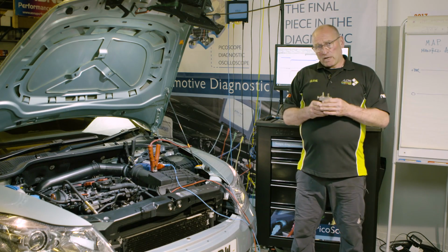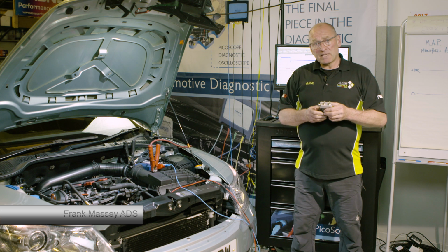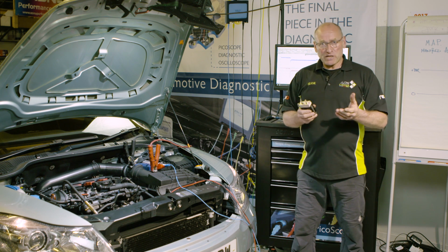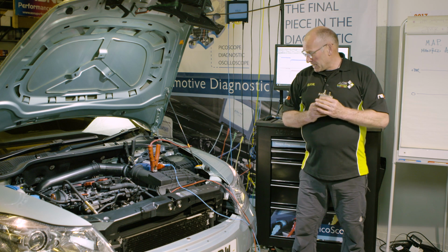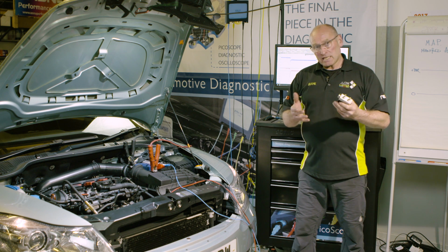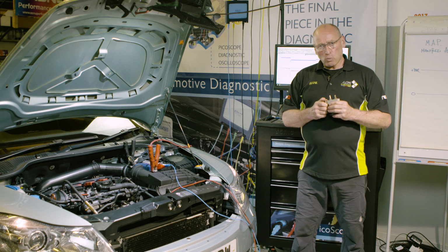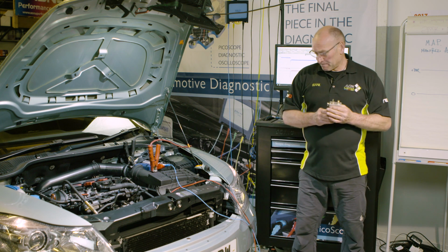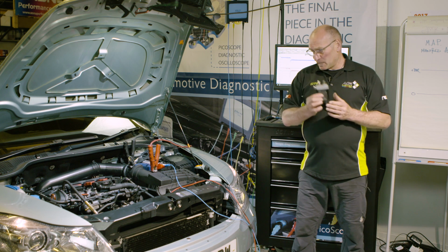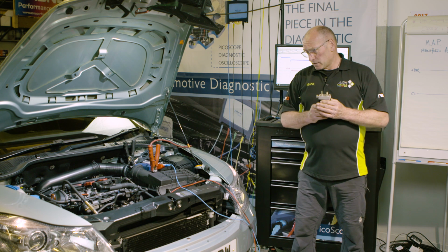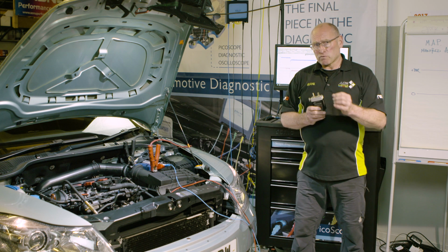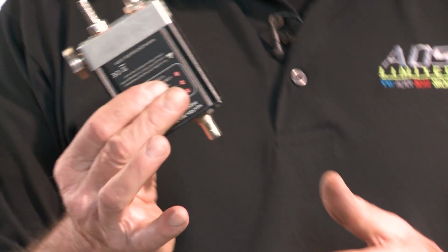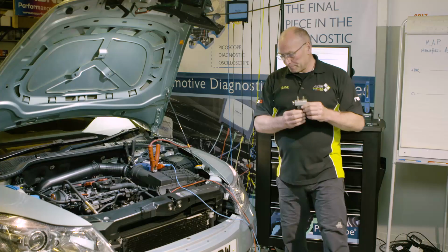Just to recap where we are, part one of the analysis of this engine was the bar graph analysis of compression variation, relative compression. We then added some detail to that by introducing the scope and looking at current variation during the cranking phases. We're now going to use the WPS. I've already got a device in cylinder 1, so we're actually going to run this engine in real time, less the spark plug in cylinder 1. I'm going to attach WPS to cylinder 1.